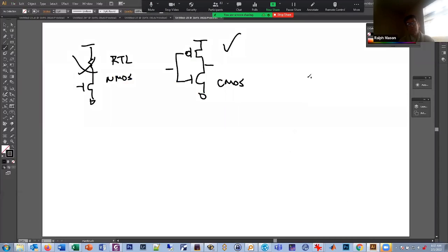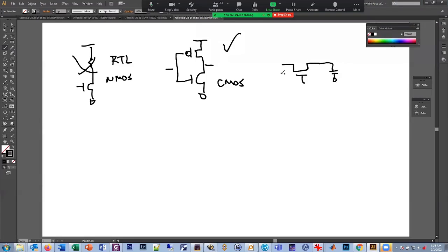So we know that if I make an NMOS switch, I'm just going to draw it upside down for now. Here's an NMOS switch. And what do we say NMOS are good at passing? If I want to pass something through to the other side here. Low. These are good at passing a low value, a zero. These are good at passing the logic zeros, but not good for ones.